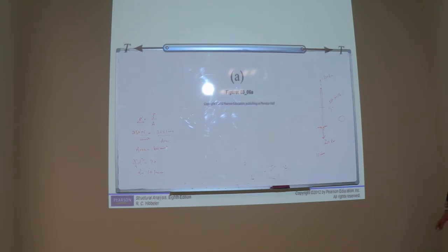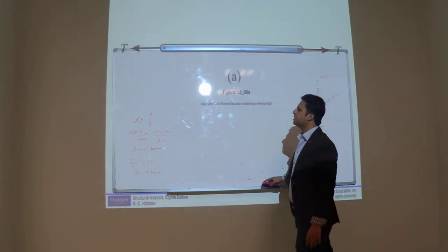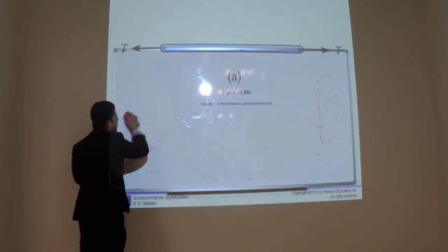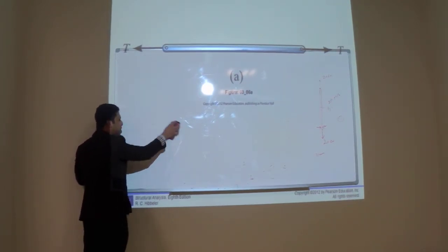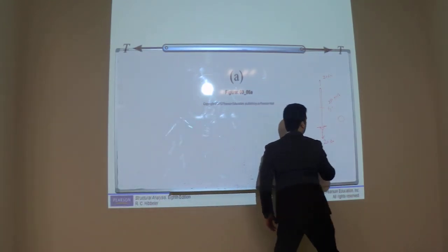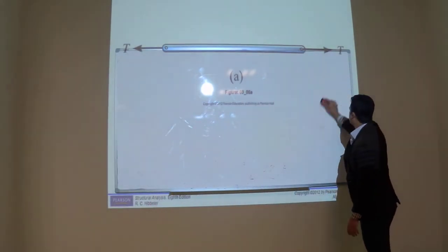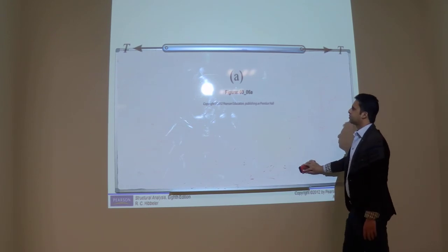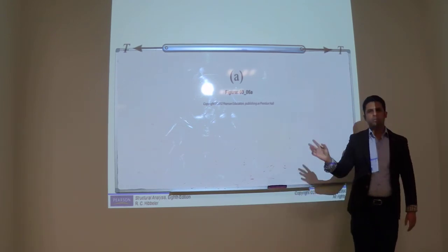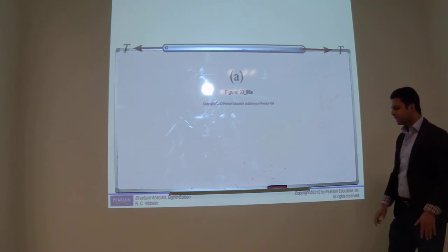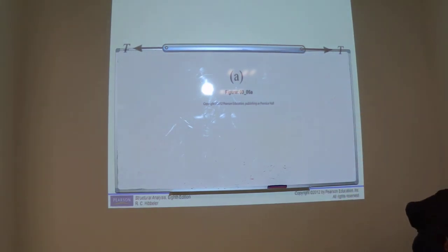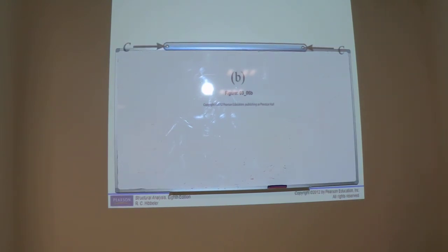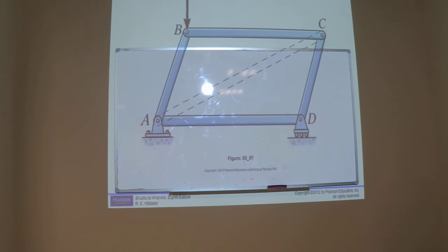That's how we design. Design is very simple for tension, but for flexure it depends on what you want to design it for. If you want to design it for compression, the procedure is a little bit lengthier because there is one more thing known as slenderness. So we design these members for compression and tension.